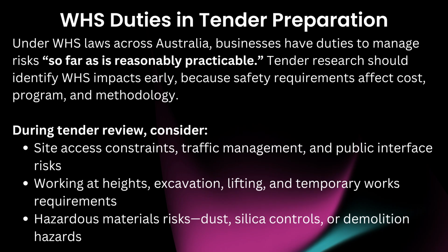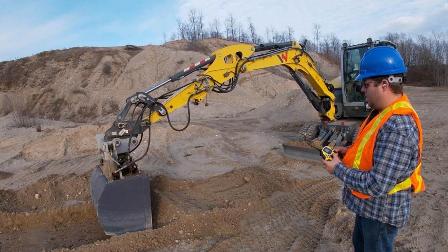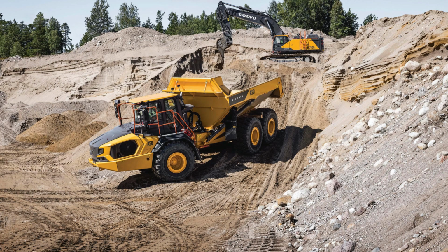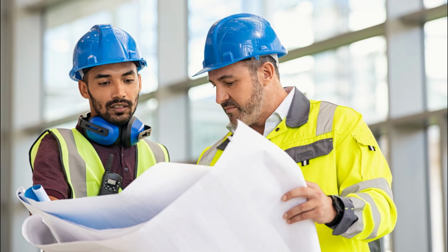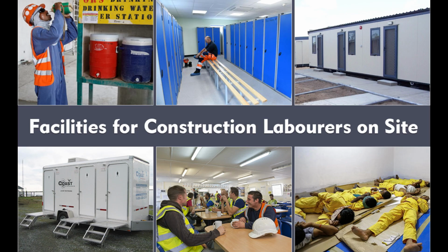During tender review, consider site access constraints, traffic management and public interface risks, working at heights, excavation, lifting, and temporary works requirements, hazardous materials risks, dust, silica controls or demolition hazards, contractor and subcontractor management requirements, inductions, supervision, PPE, permits, site amenities and compliance needs, fencing, signage, site security, emergency planning.